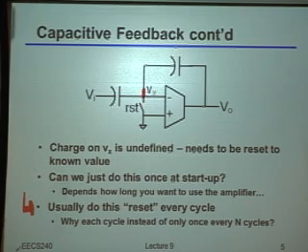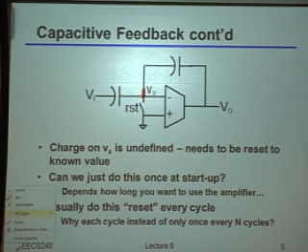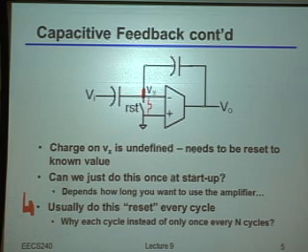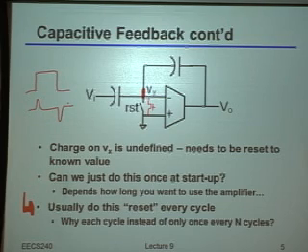So very commonly, and we'll talk a lot more about this later on down the road, if you were to build that, for example, out of an MOS transistor, then every time you were to turn that transistor on and off, if you looked at the current flowing through it, even independent of any change in voltage it was making, you'd basically see these glitches in current from charge coming into the channel or being forced out of it. Okay? So that would mean that every single time you turn that switch on or off, there's probably going to be some residual error on that Vx node. Okay?